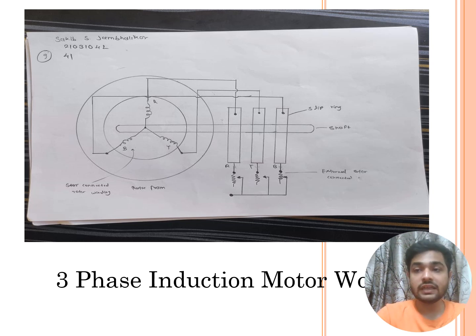According to Faraday's law of electromagnetic induction, the EMF induced in any circuit is due to the rate of change of magnetic flux linkage through the circuit. As the rotor windings in an induction motor are either closed through external resistance or directly shorted by end rings, they cut the stator's rotating magnetic field, and an EMF is induced in the rotor copper bars. Due to this EMF, current flows through the rotor conductors. Here the relative speed between the rotating flux and the stationary rotor conductors is the cause of the current generated.